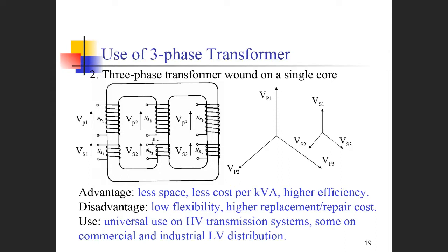In the case of the three-phase transformer bank, for the same rating power, say 1000 kVA, each of the three single-phase transformers has a size that provides 330 kVA. So their size is smaller, and you can transport them one by one.